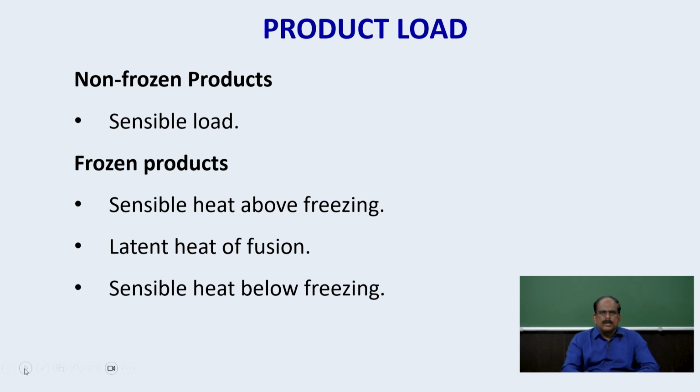Again, for non-frozen products, only sensible load will be there. There is no latent load. Whereas if you take a frozen product, both sensible load as well as latent load will be there.